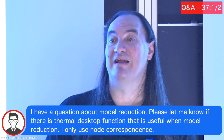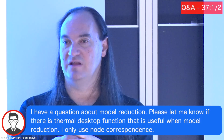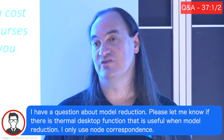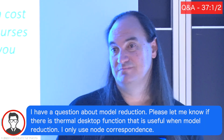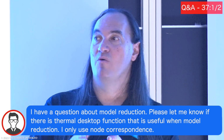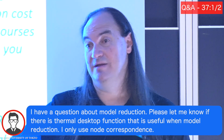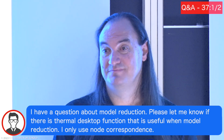So node correspondence is similar to what you were saying. Let me take these 1,000 nodes and I'll represent them as 100 nodes or 10 nodes instead. So you're just collapsing multiple nodes into one. But even if you did the node correspondence, you still have to figure out what are the conductive couplings now between the nodes that remain, which is a challenge to do. I see.